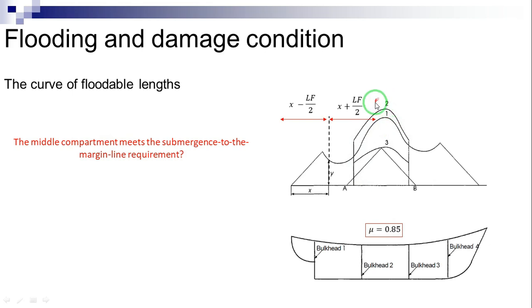Let us further assume that we are dealing with a ship subject to a 2-compartment standard, factor of subdivision F equals 0.5. Then we divide by 2 the ordinates of the curve 2, obtaining the curve marked 3. This is the curve of permissible length.